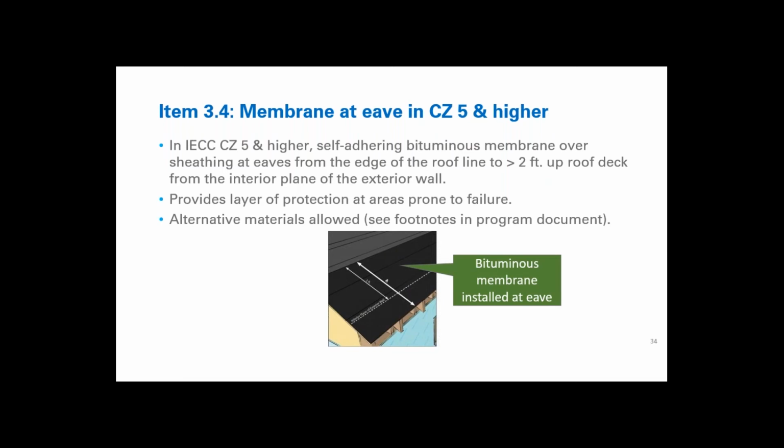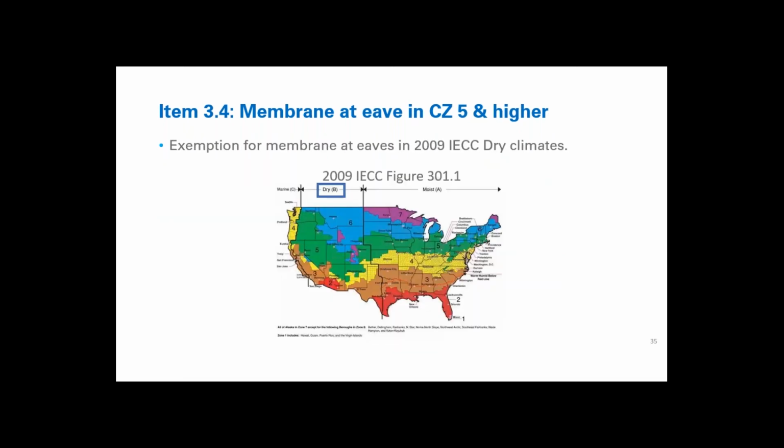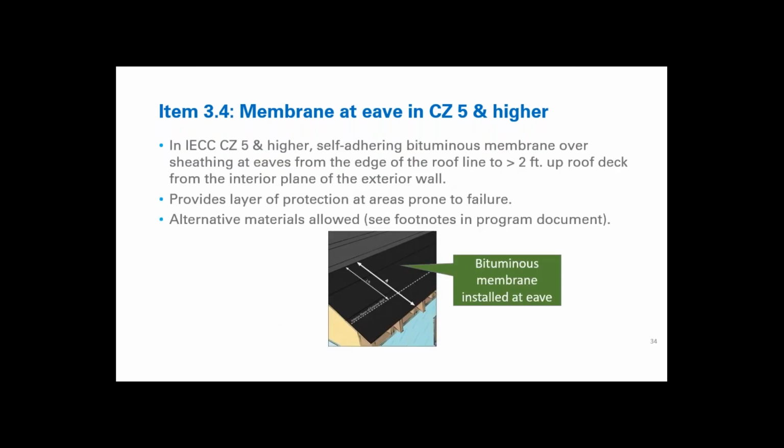This next one's going to be CZ5 and higher, and I'm going to move through it pretty quickly, which is to say you also need this membrane installed at eaves in CZ5 and higher.